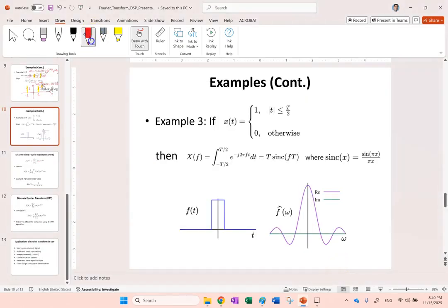So this was the rectangular time signal, which is time limited. But if you remember the frequency content of it, this guy keeps going forever. Although it gets smaller and smaller, it becomes zero only when omega or f goes to infinity. So in the frequency domain, this signal is not limited, only in time it is limited.